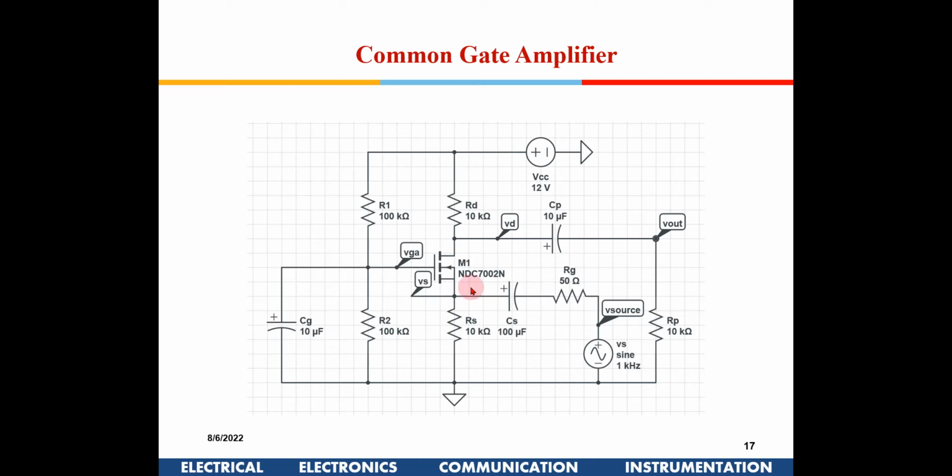The voltage gain is between the source and the drain only. This capacitance is very low, and since it doesn't get multiplied by the gain, there is no issue with high frequency applications. Is this aspect clear to all of you? Yes, sir.